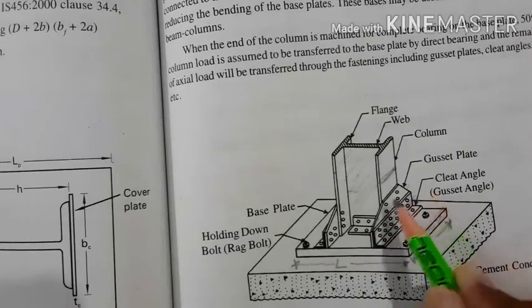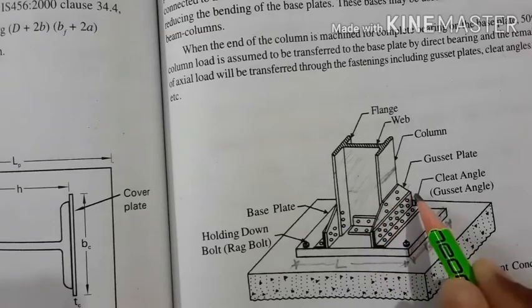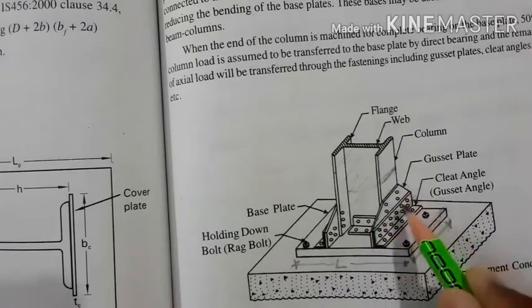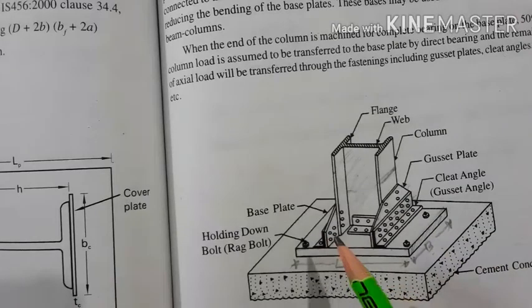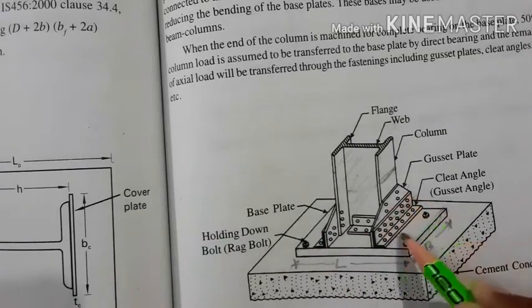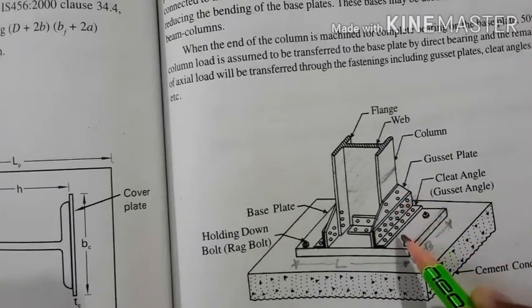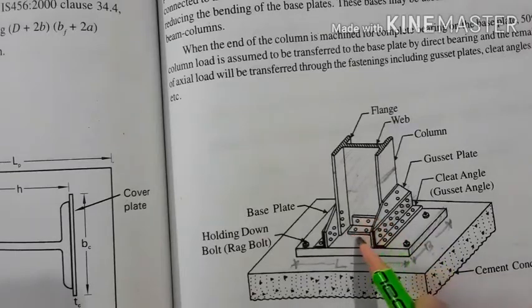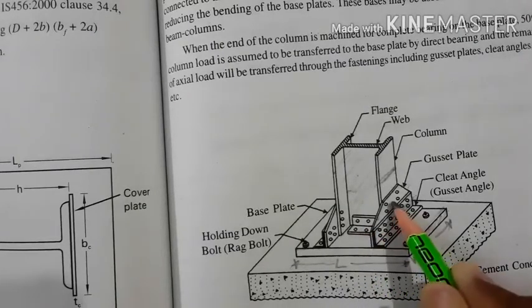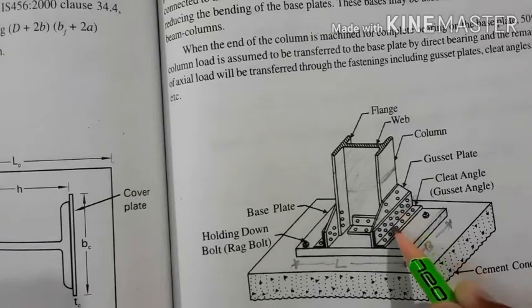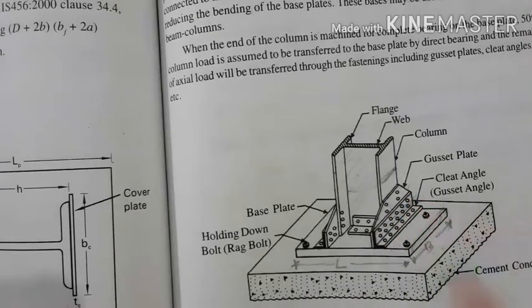Now whatever number of bolts you have got, 10 bolts, to be provided on one side, then 10 plus 10, the total number of bolts required is 20. The 10 bolts you have calculated are for one side. Now you have to arrange the bolts. This is the web cleat angle, a nominal angle to be provided, and the nominal number of bolts to be provided here, 4 bolts. Since the gusset plate is connected to the angles, this angle is called a gusset angle. I hope you understood this figure.